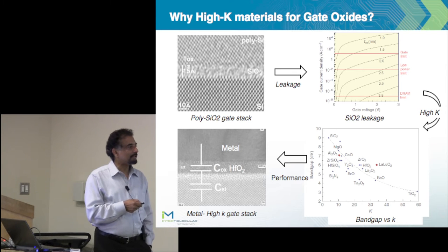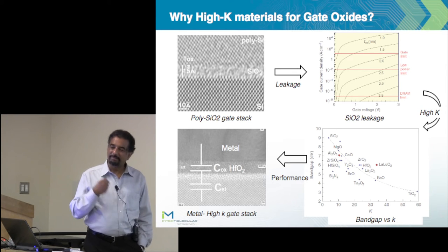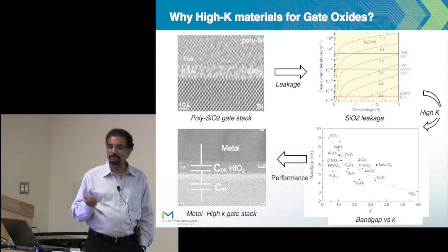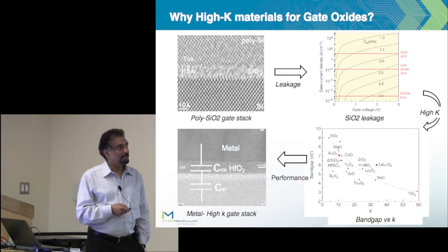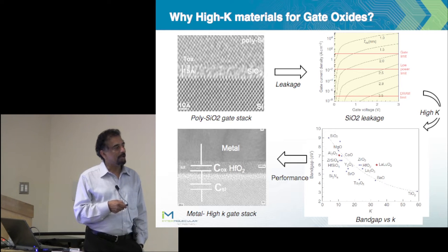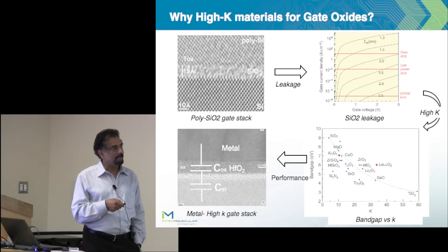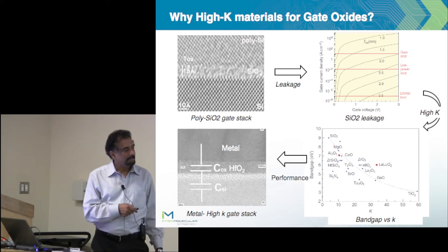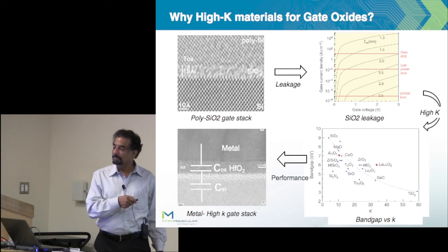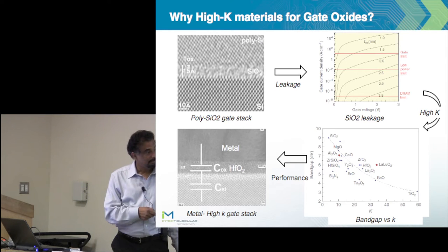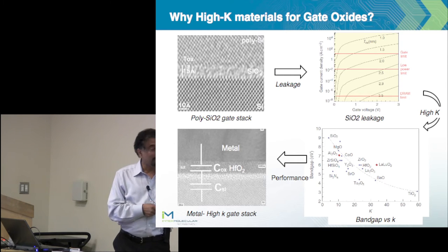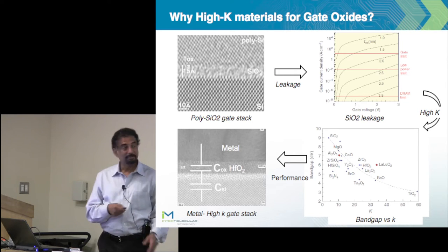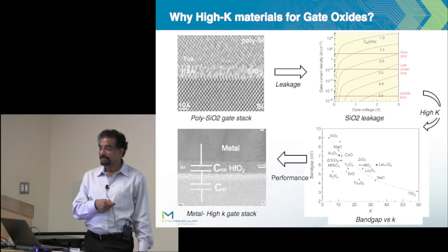So what happens is that you say, okay, I need a band gap that gives me enough margin, somewhere around 5 to 6, and you wind up with things like hafnium oxide and lanthanum oxide, and eventually everybody moved into hafnium oxide. So it's a question of this: the K is too low, but the band gap is great. That's for silicon dioxide. You go over here, the dielectric constant is high, but the band gap is low. So you have the Goldilocks effect, which is just right.